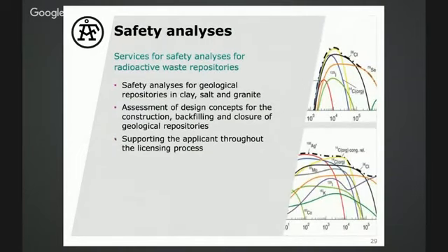These simulations are then the basis for so-called safety analysis, where the goal is to quantitatively show that a repository is safe over a million years. And what you see here in the image to the right is typically a result of such a numerical safety analysis simulation. It gives you curves that determine a radioactive dose associated with certain radionuclides for a typical human living close to a repository, at the surface. So the additional dose he will take up because there is a deep geological repository underneath his feet. Now this dose is not supposed to exceed a certain threshold that is given by law. So these simulations particularly help to support the applicant, which in Switzerland is NAGRA, through the licensing process.